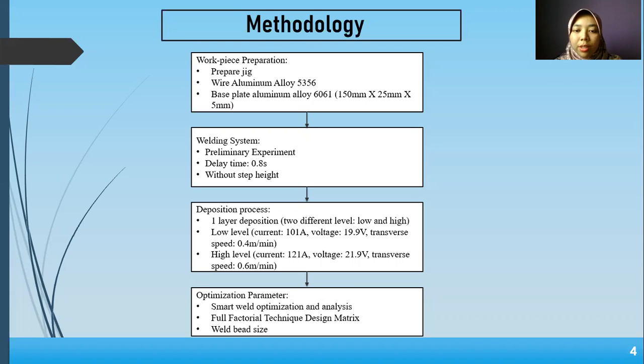Next, welding system. Do a preliminary experiment involving a delay time of 0.8 seconds. The importance of the delay time, based on the previous study, is that an increase of the delay time significantly influenced the heat accumulation along the construction of the part, and the preliminary experiment is produced without doing step height. In the deposition process, a sample set of parameters consisting of low and high parameters has been chosen to build one layer deposition.